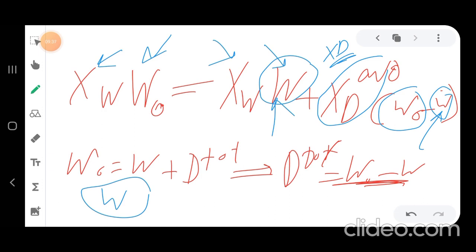This can be done in 2 ways. The first is to maintain a constant reflux ratio, which is the easier way. As you maintain a constant reflux ratio, consequently you will have a variable xd. The other way around is to play with the reflux ratio in order to maintain a constant xd, which is somewhat more difficult.